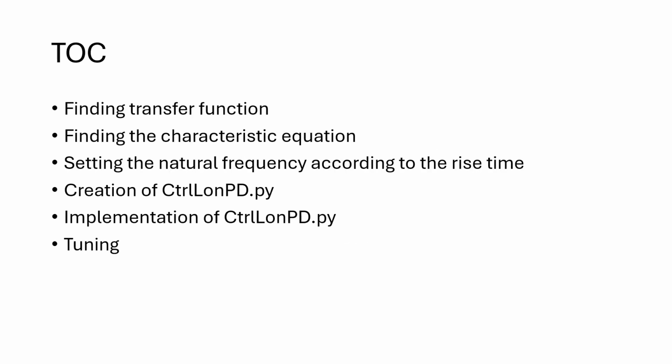So for this lab, I'll just go over what we touch on. I'm pulling this from the textbook and from some things that I know as a TA. So we'll be going through finding the transfer function, as well as finding the characteristic equation, setting the natural frequency according to the rise time, some of the creation of the controller file, as well as the implementation of that controller file in your simulation, and then some thoughts on tuning as well.